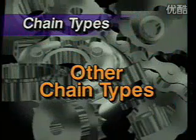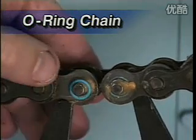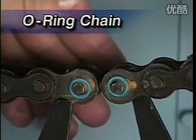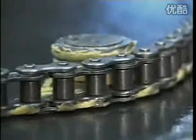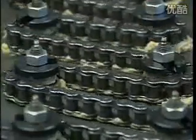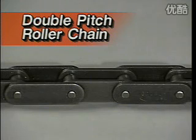While roller chain is the most widely used chain, industry relies on numerous other designs for special applications. Some of these designs include O-ring chain, a variation of roller chain designed for applications where relubrication is difficult, expensive, or impossible. The chain contains small O-rings in each link that seal in lubricant so that wear on internal pins and bushings is minimized. And the O-rings also seal out dirt and moisture, keeping pins and bushings free of damage from abrasion or corrosion.